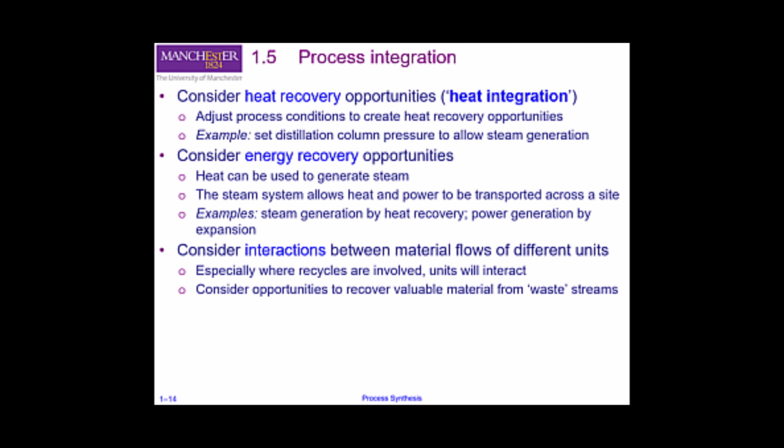Next, we considered process integration in terms of integration of material flows within the process. We need to take a system view in order to understand how recycle impacts on the flowsheet performance. We should also consider how to recover, reuse, or upgrade material within the process that would otherwise end up as waste. Okay, so sometimes you might want to recycle or further process your waste. Or you might want to actually use a subsequent reaction system to further process your waste and then sell it to the sellers.